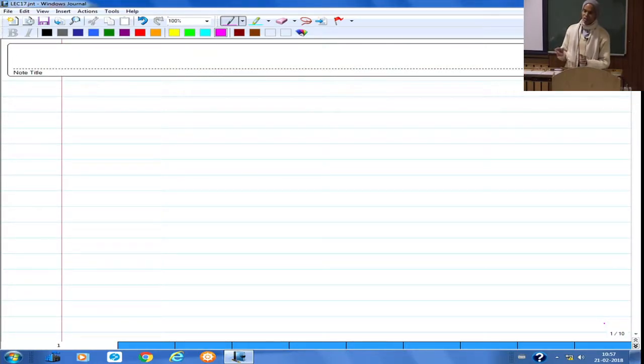Actually, I also included the axial deformation. Timoshenko means it is only basically bending degrees of freedom, so V and theta. But I included axial displacement also. So if there is only transverse load, you can drop out U naught, and then you will have basically V and theta as the variables. So maybe I'll discuss when I start.